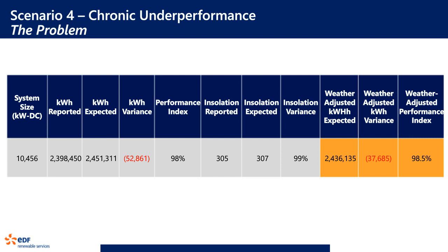And that's interesting, Larry. I mean, you're walking yourself through a problem here. You have a very large problem. You're working through a trial and error process where you're testing all the mechanicals. You're doing analysis on inverters, comparing 2 and 3 and 4 to make sure that they're operating correctly. You're running through calibrations and finally going through IV curve tracing. All of this obviously is coming to some solution whereby you're recapturing some losses, but you're not getting to the root of the problem. Owners typically will not accept underperformance perpetually.